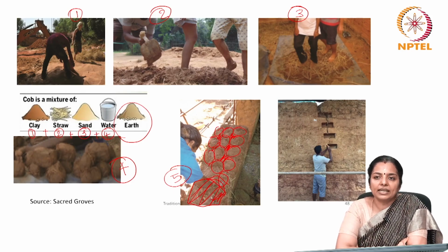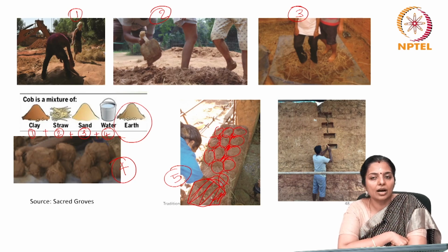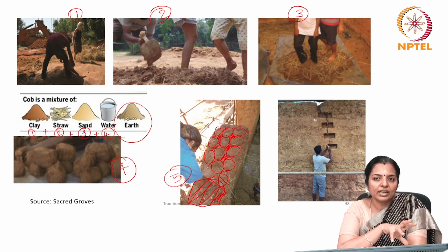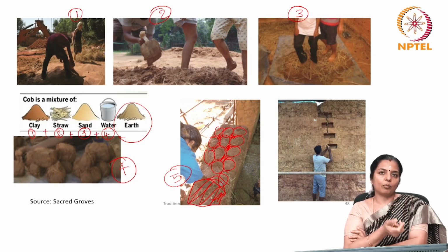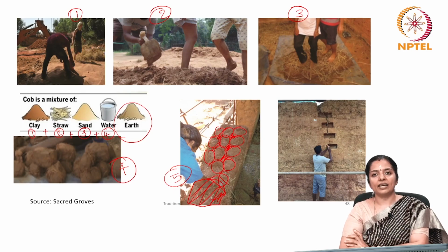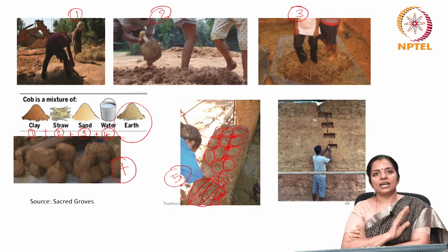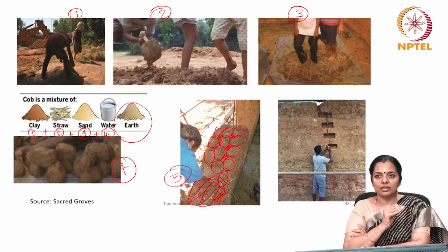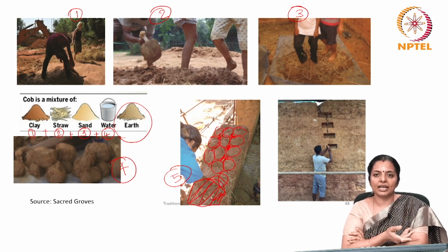The straw in the upper layer descends and it links with the straw in the bottom layer when it is forced against some pressure with a sharp object. This creates a stress and binds the structure together. The straw from top layer and bottom layer have to get interspersed rather than remain as separate layers or separate balls. So, place the balls one next to the other and then start adding some pressure with some sharp object or a reinforcement rod or a shoe or something like that, and make it into one homogeneous layer.